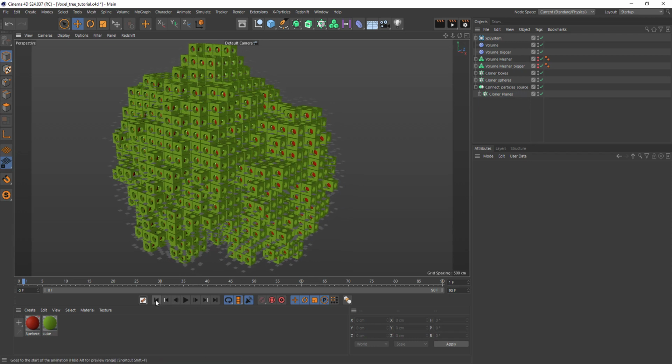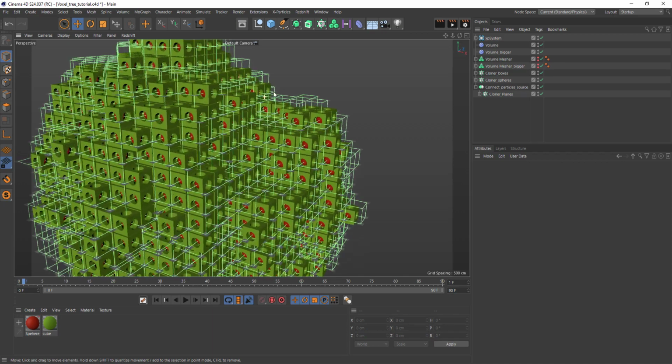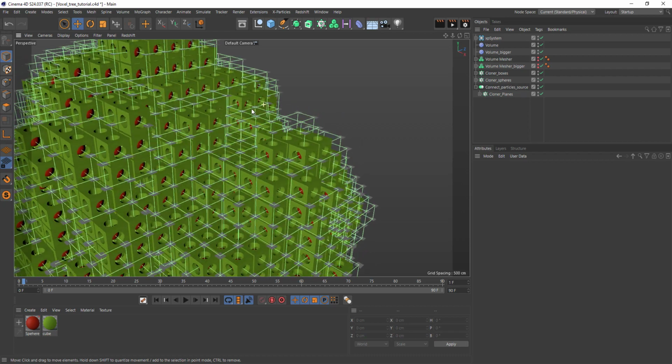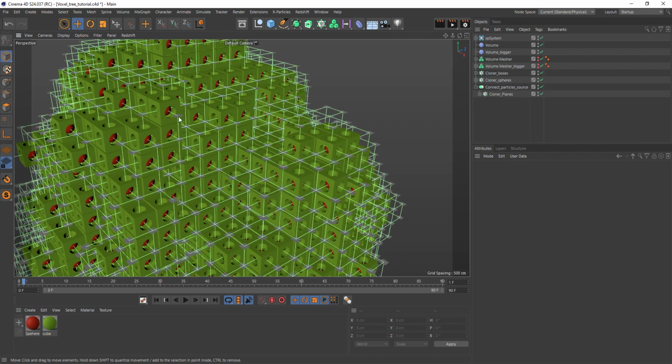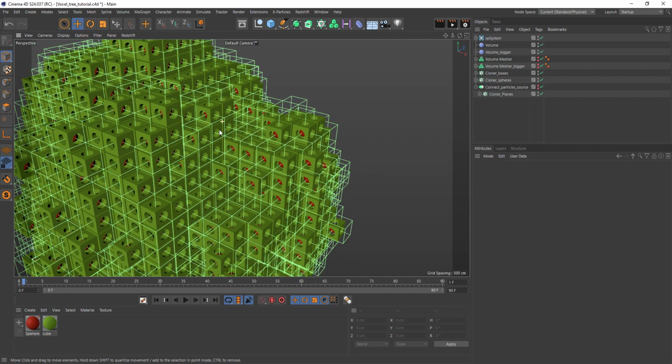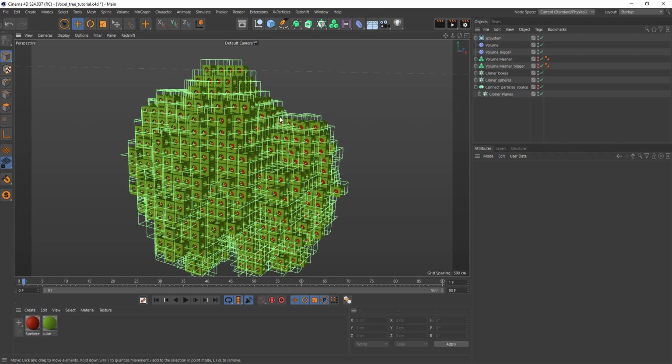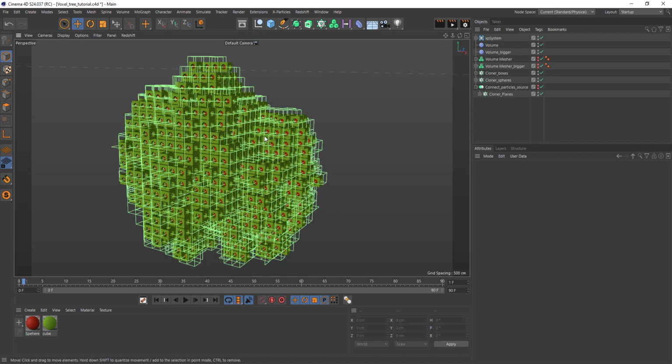And if I rewind and press just one frame forward, we're going to have this beautiful structure, because the particles are getting born from the new mesh, right? So I'm going to turn off my connect particles, and now we have this beautiful voxel grid with the outside mesh, outside wireframe structure. Now we need to see how to render these lines, right?